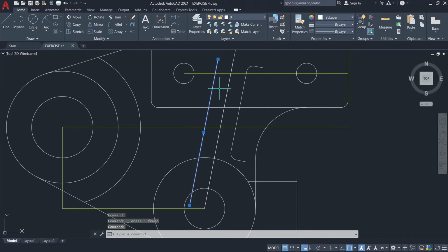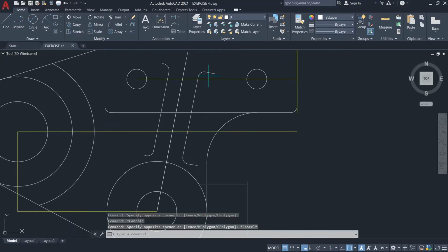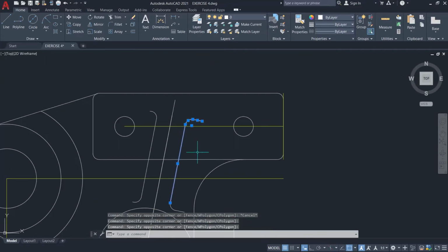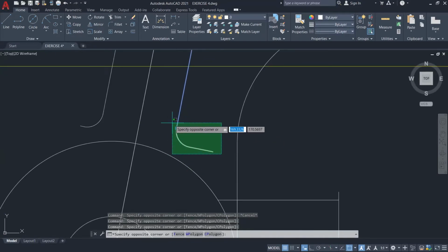While in the right offset line, from this endpoint, make a line by 1.76 downward, or just offset the left 1.76 line. Then from the two endpoints, make a line measuring 0.15 to the left. Then, fillet it again by 0.12. Then remove the offset line and the excess lines. Then, change the color to green with its line type of dashed line or hidden line.